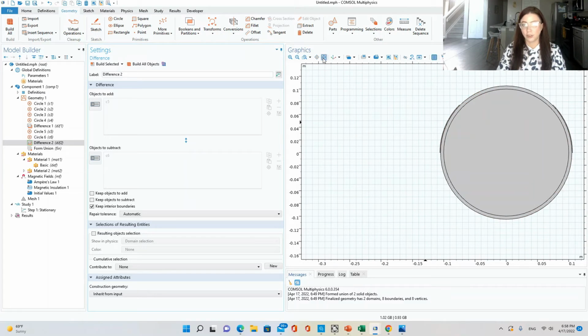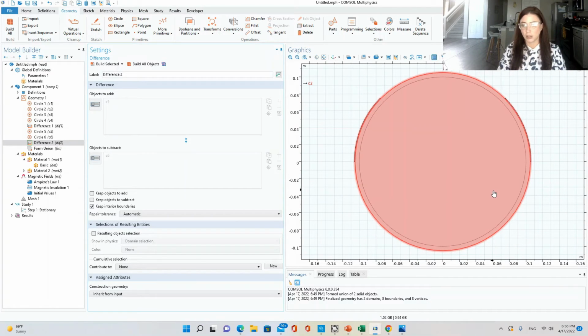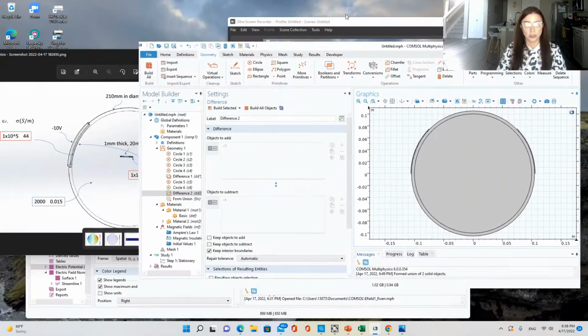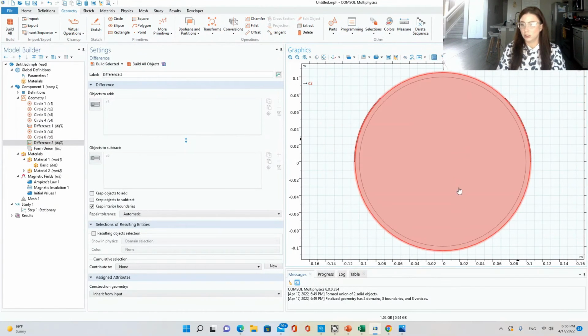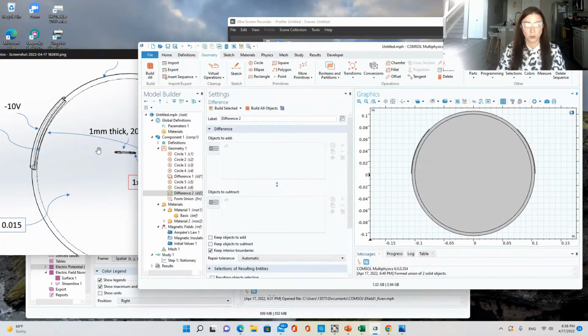Now what I haven't done yet in the last model, but I will in this one, is create these center electrodes. So this little thing in the middle. So we're going to have one horizontally located and then change it to be vertically oriented, and do simulation both ways. So it looks like a rod. So I could either go with ellipse or rectangle.